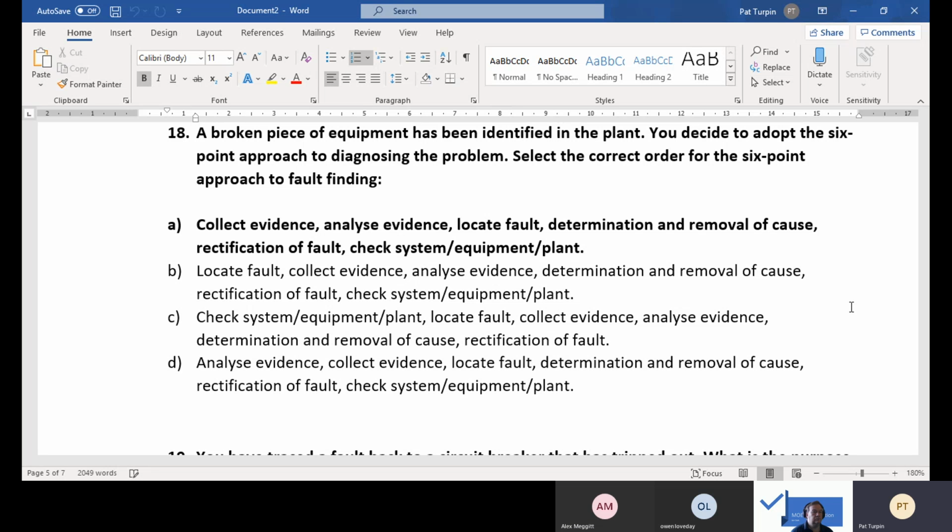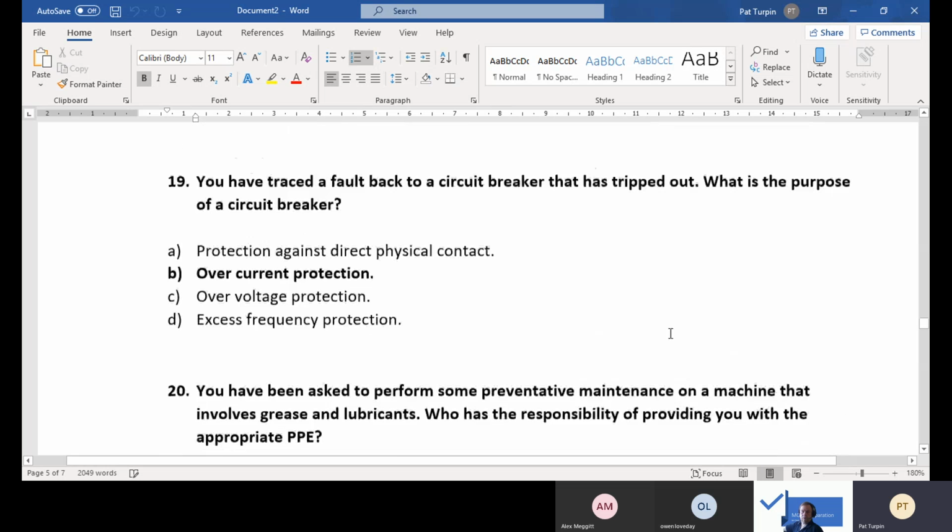Most plant people have got it instilled into them now. Turn up on the job to check something: right, prove to me it's turned off. Who's locked it off? Right, well, I'm adding to that. And that's another thing to remember: add your lock to something if you're working on it as well. Then even if the other person takes theirs off, you still know it's locked off. You know the procedure, guys. I won't bang on about it. I know Ian will have covered it brilliantly with you anyway.